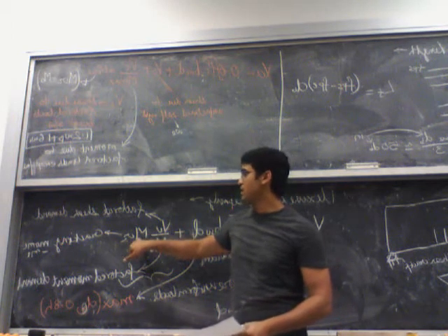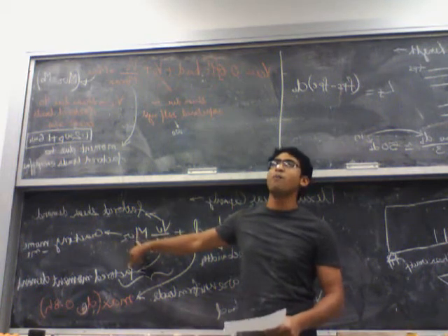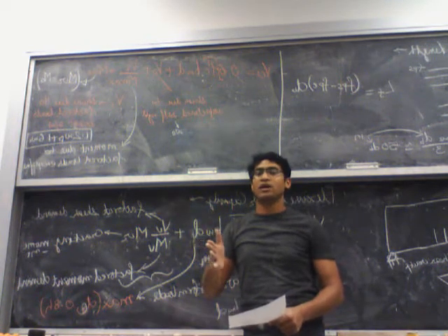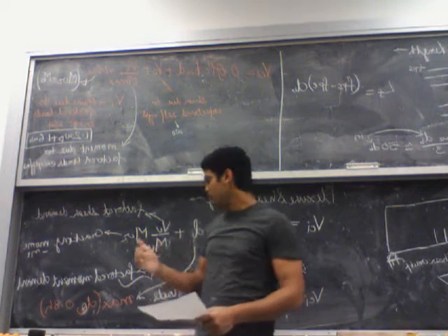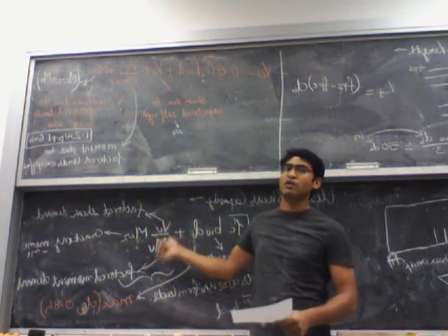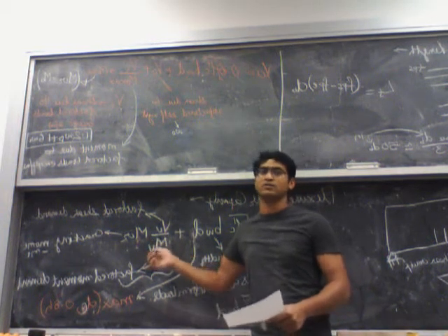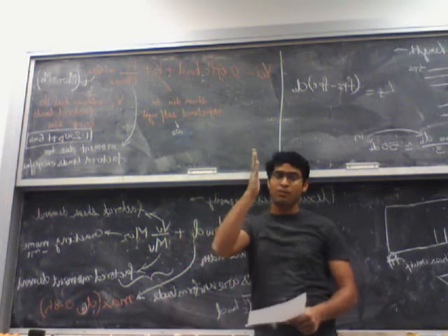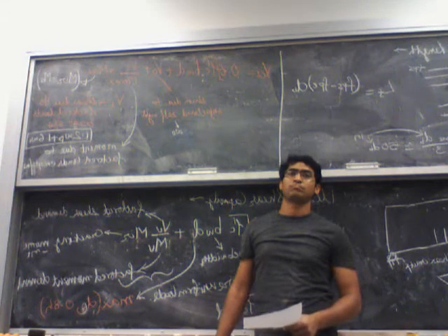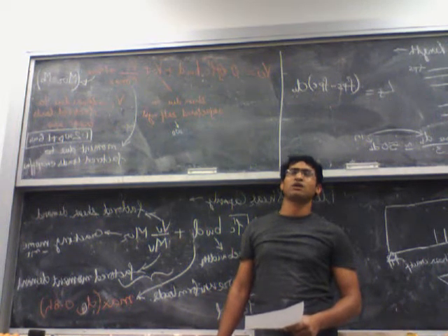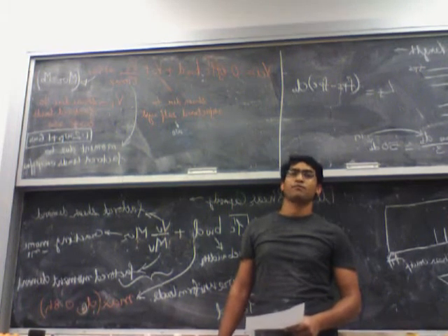So what you have is the moment which will create that first flexure crack, and you want to convert it to a shear which will create the first flexure crack. So you multiply it by this factor of Vu over Mu, and it gives you what shear will produce that flexure crack. Find out the shear capacity of the concrete. Does it make sense or not?